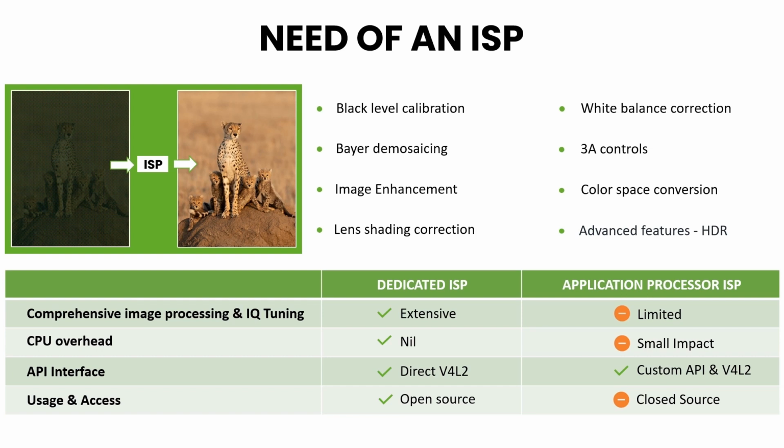I'm going to talk about some of the points to keep in mind while using a dedicated hardware ISP versus using an ISP in the host processor. Using a dedicated ISP almost always gives you a lot of flexibility in terms of fine tuning. The tuning may be in terms of frame rate, image quality, resolution, and so on. However, when using the integrated ISP in the host processor, the options could be limited.